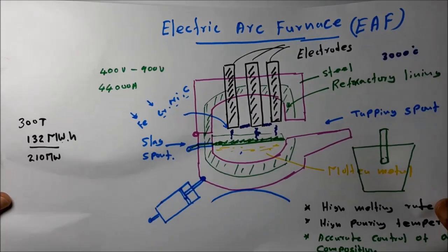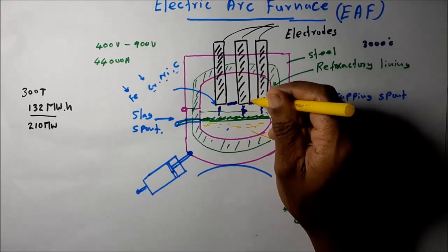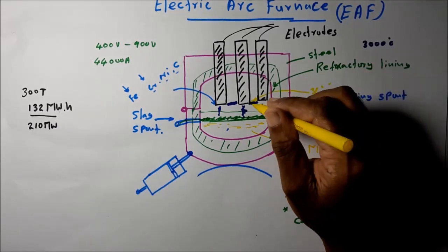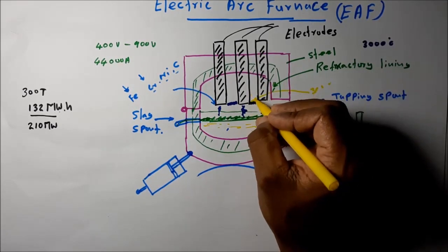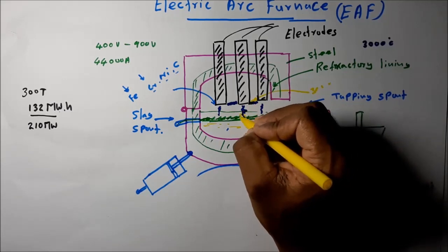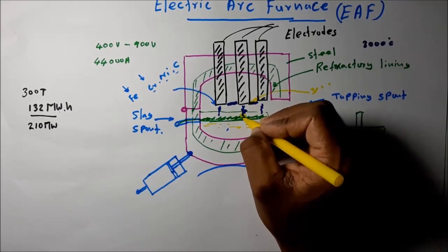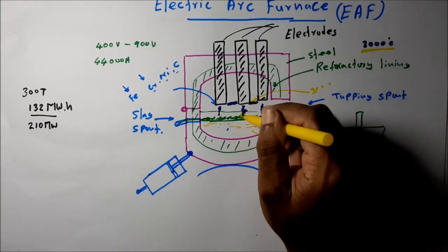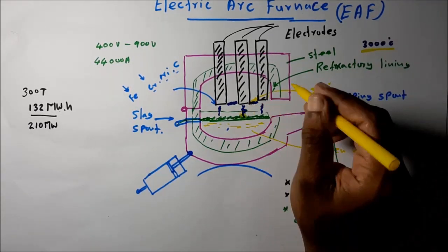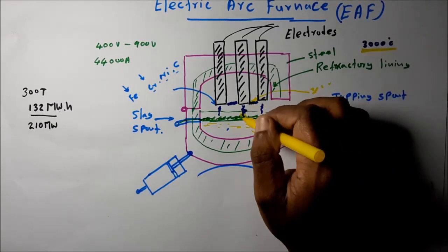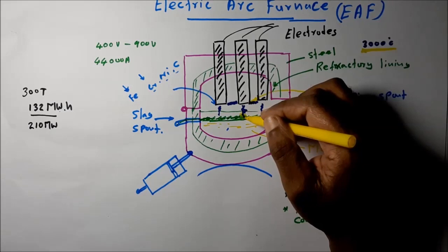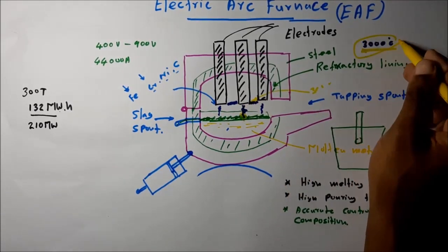It produced a very high temperature electric arc, around 1300 centigrade. The material in this region may oxidize because of this high temperature. The alloying elements may degrade, or their chemical properties may change, because of this high temperature electric arc.